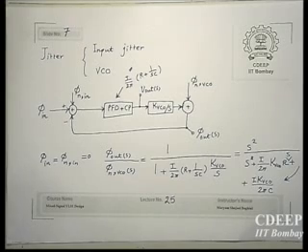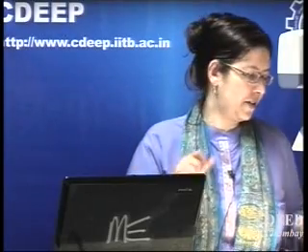Very interesting. That's a high pass. Oh, sorry, I missed the time today. So it's a high pass transfer function. So for phase noise of the VCO, the loop transfer function is high pass.